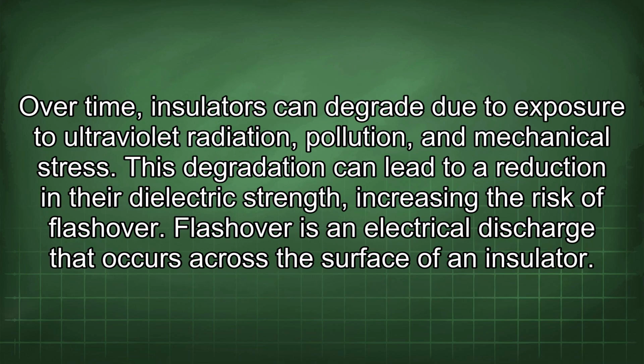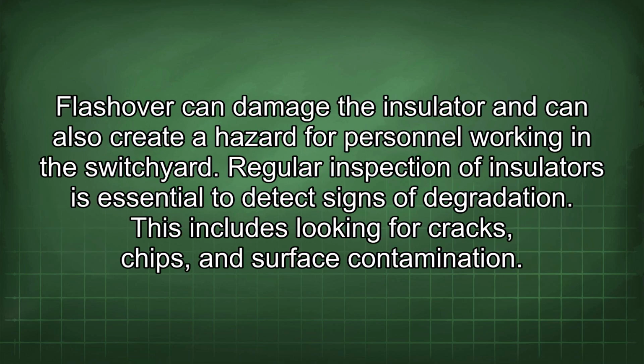Over time, insulators can degrade due to exposure to ultraviolet radiation, pollution, and mechanical stress. This degradation can lead to a reduction in their dielectric strength, increasing the risk of flashover. Flashover is an electrical discharge that occurs across the surface of an insulator. Flashover can damage the insulator and can also create a hazard for personnel working in the switchyard.